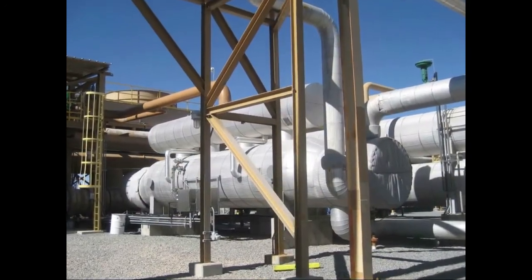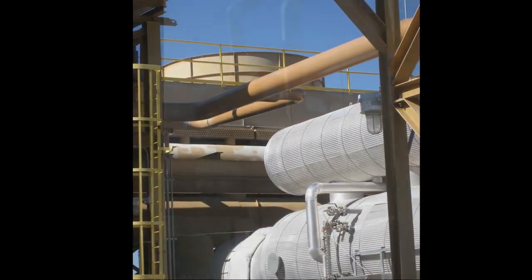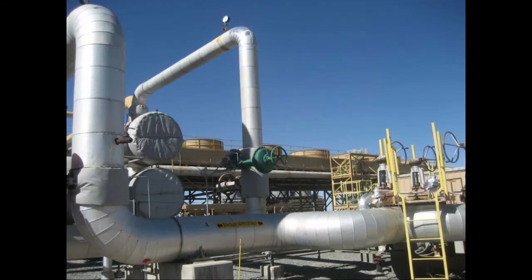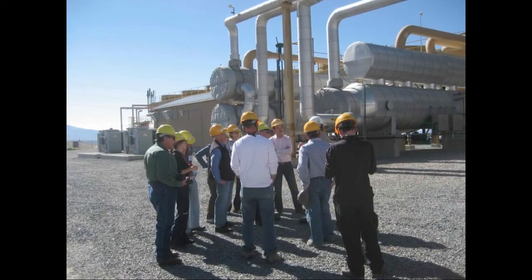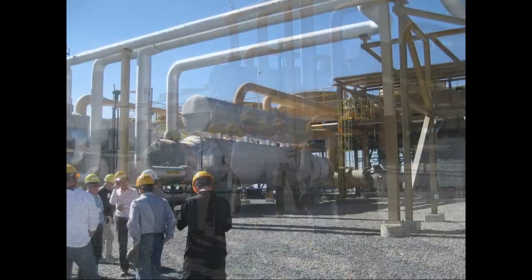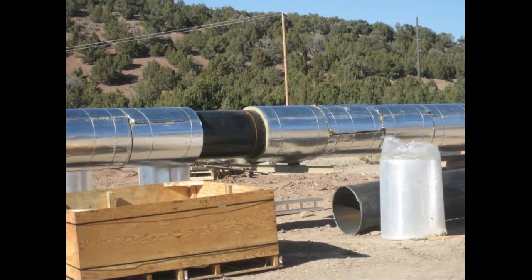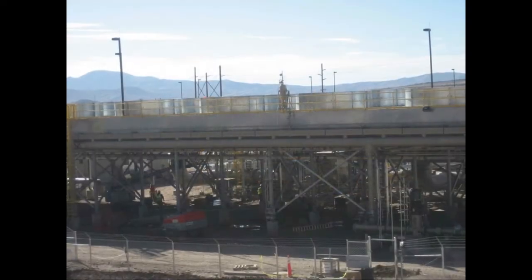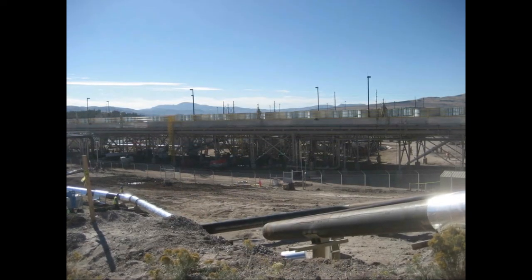And this is the flash plant. So this is where you put the steam in contact with something like isopropanol, which has maybe a boiling point of 35 centigrade. It flashes to steam even below the boiling point of water. In a closed system, it flashes to steam by evaporating, runs through a turbine, generates electricity, and then is condensed back below 50 degrees centigrade, and then becomes a fluid. So in other words, you can actually get steam out of water below 100 degrees centigrade because you're transferring the heat to another fluid, which is able to boil at 36 degrees centigrade.